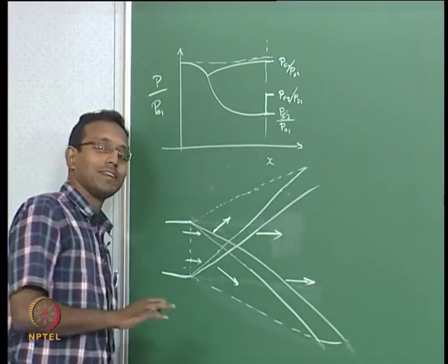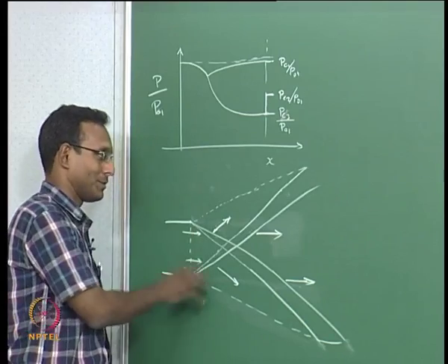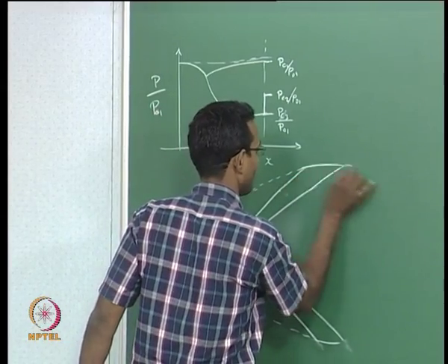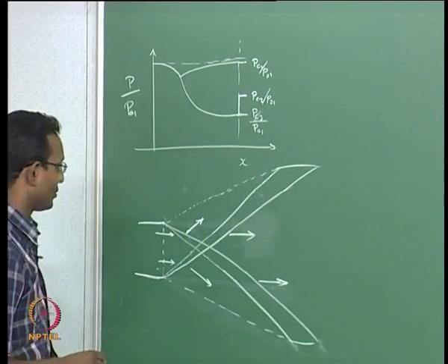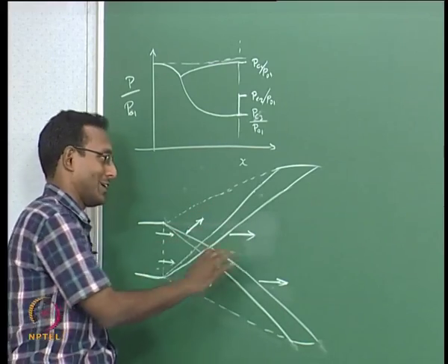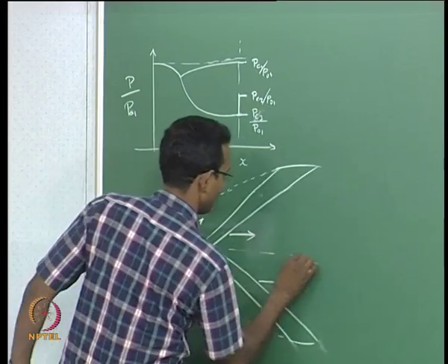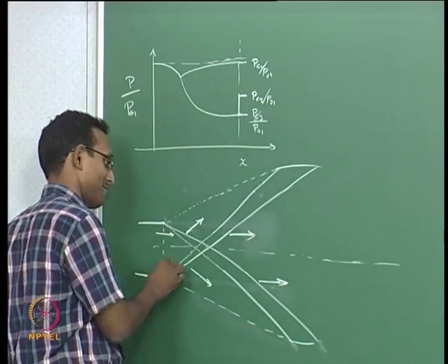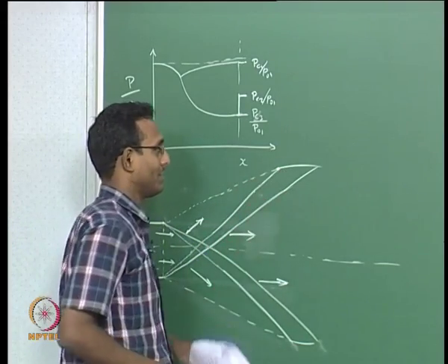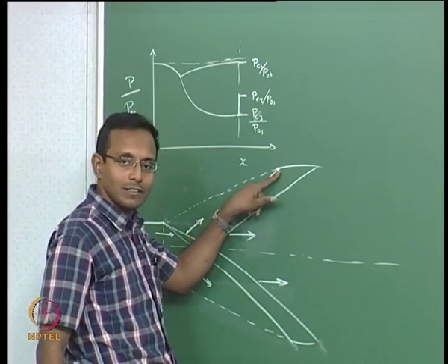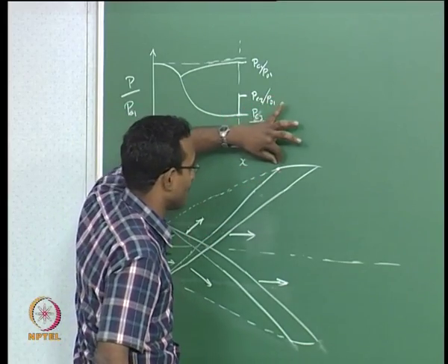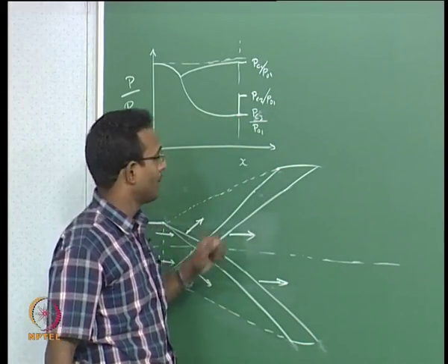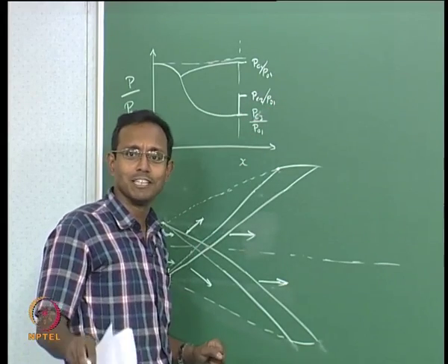Okay. So, we will not pick that complicated case, we are going to assume symmetric problem, both pressures are exactly equal. I am not drawing it very symmetrically, but it is supposed to be symmetric, okay, doing something like this. So, let us say I won't draw both sides and try to make it symmetric, I will draw only one half. It is the simplest way to get through in engineering style. So, I am going to say I have this compression wave, expansion wave coming here, and now at this point this expansion wave is just telling the outside atmospheric fluid that it has to decrease pressure, but the outside atmospheric fluid is going to say no, I will never change my pressure.